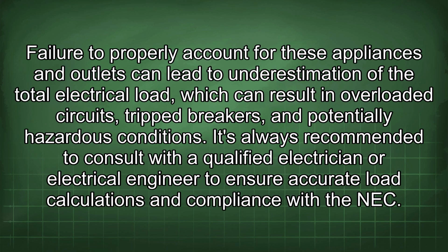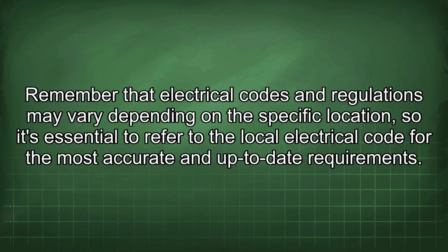Failure to properly account for these appliances and outlets can lead to underestimation of the total electrical load, which can result in overloaded circuits, tripped breakers, and potentially hazardous conditions. It's always recommended to consult with a qualified electrician or electrical engineer to ensure accurate load calculations and compliance with the NEC. Remember that electrical codes and regulations may vary depending on the specific location, so it's essential to refer to the local electrical code for the most accurate and up-to-date requirements.